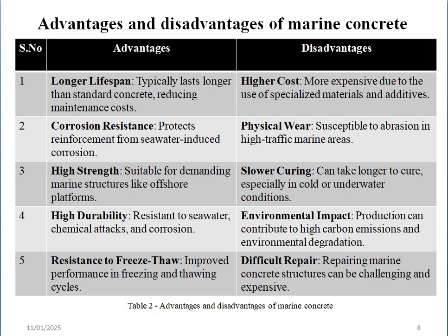Disadvantages: higher cost. Marine concrete is more expensive due to the use of specialized materials and additives. Physical wear: it is susceptible to abrasion in high traffic marine areas. Slower curing. In cold or underwater conditions, marine concrete can take longer to cure.